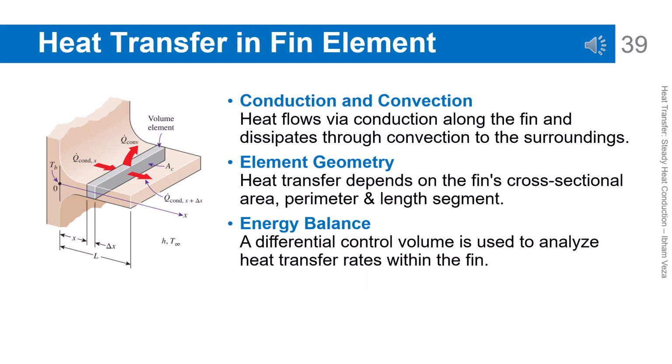Heat transfer in finite element. Heat flows by conduction along the fin and is dissipated to the surroundings by convection. The analysis is performed using a small differential element as a control volume. Fin geometry, such as cross-sectional area and perimeter, strongly influences the heat transfer rate. An energy balance on the small element is used to derive the fin differential equation. This approach forms the basis of all fin analyses.